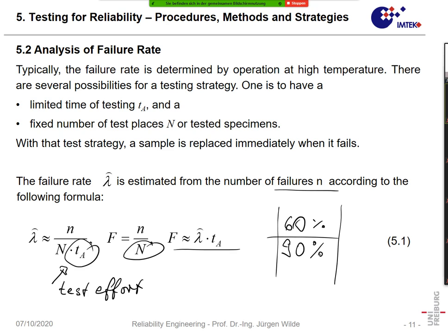And here you must give certain failure rates, and these failure rates must be higher than the failure rate you get from your initial test. Why is it so? Here you do not know how much you can rely on these data, because you only have a few failures from a certain test effort, and now you must take into account more factors.